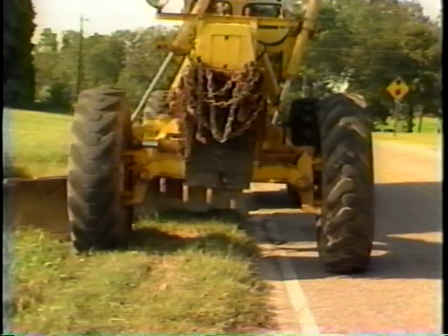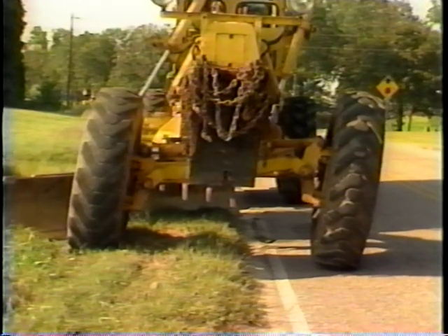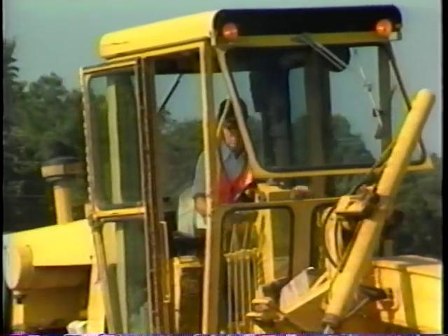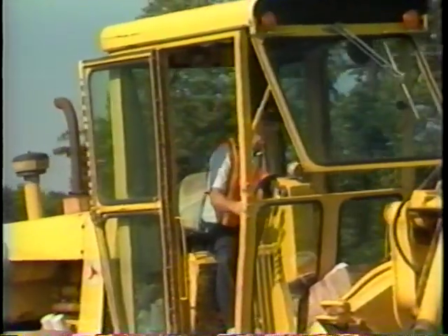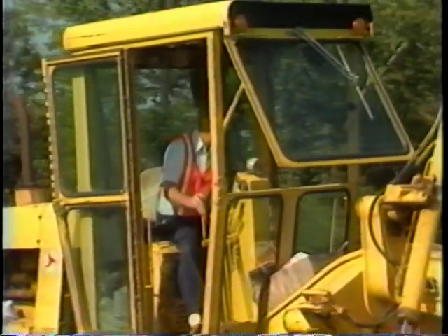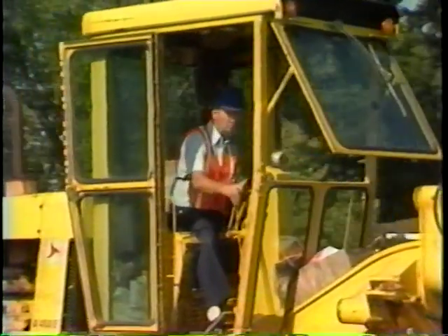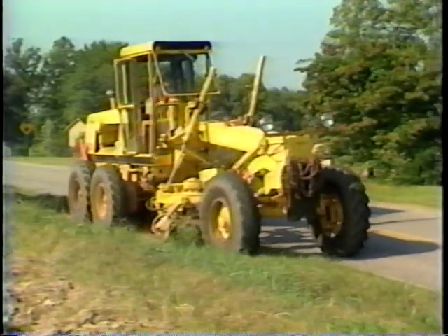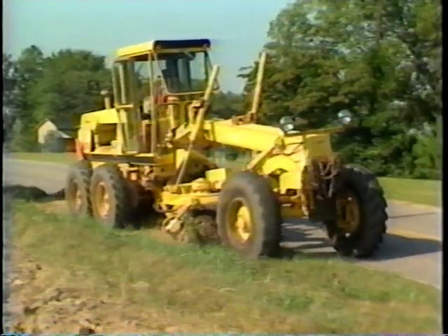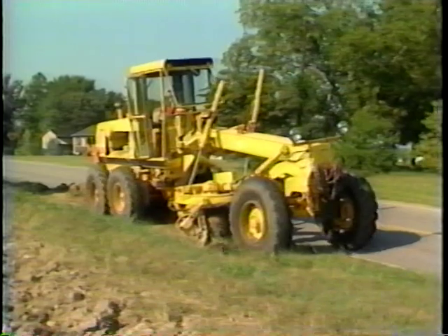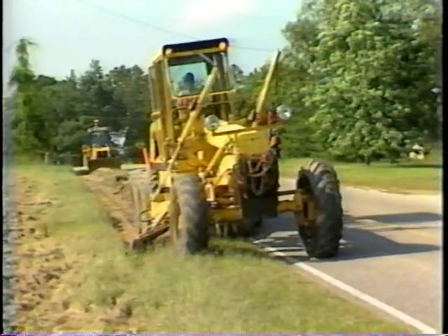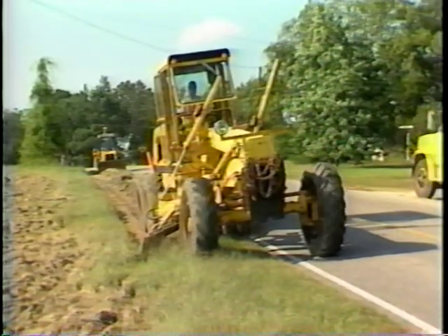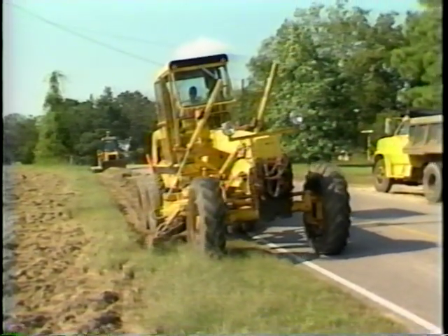Use a front wheel lean of 10 to 15 degrees in the direction that the material is to be moved. The motor grader proceeds at no more than 3 to 5 miles per hour. This prevents the blade from bouncing and creating an unevenness in the shoulder. As the motor grader moves along, the blade cuts away the high spots of material and windrows it along the edge of the pavement. Cut the shoulder to the desired slope.